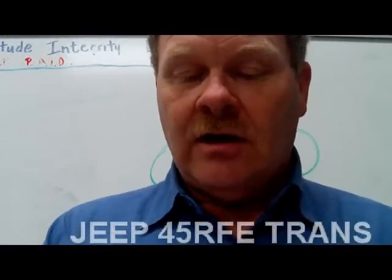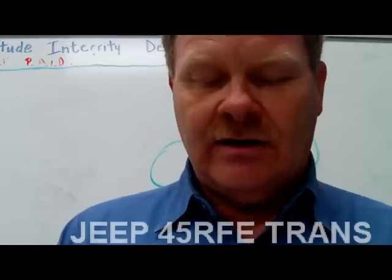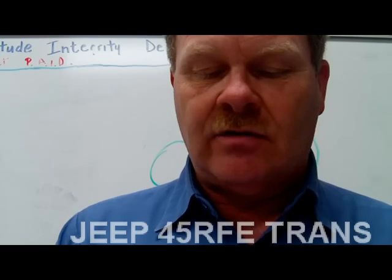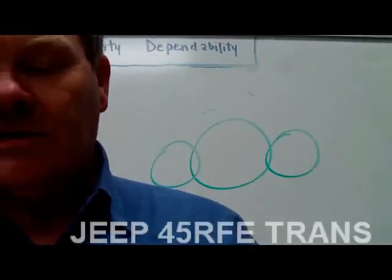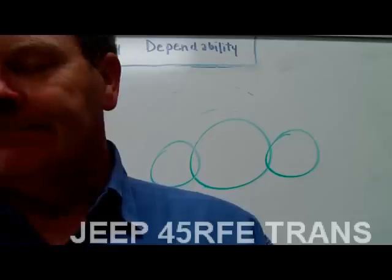In fourth gear, in overdrive, the overdrive and fourth clutches are used to obtain a final drive ratio of 0.75 to 1. What about third gear? Third gear, let's see, we've got to make sure we know what we're talking about here. In third gear, the second clutch is released and the overdrive clutch is applied with the underdrive clutch. Got that?